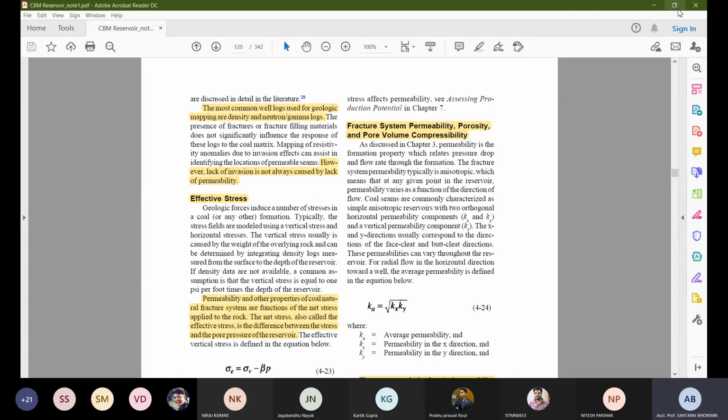then come the assumptions. In the laboratory, we always apply the pressure in the xy direction, and z is the vertical direction. So in the xy direction, the lateral pressures are the same, whereas in situ, in the field, this is not the same. The two horizontal stresses, h1 and h2, are more or less different in most cases.